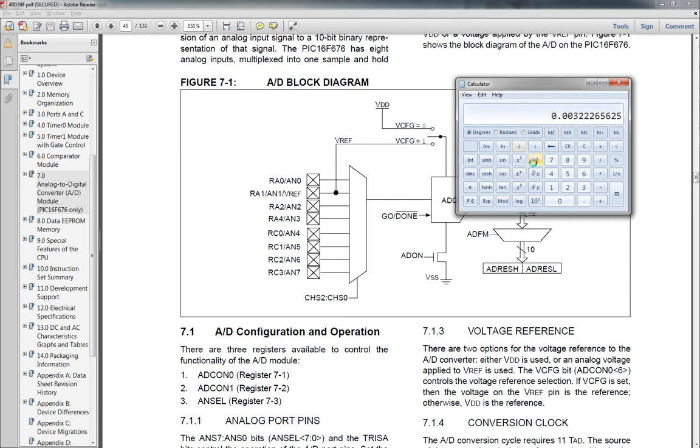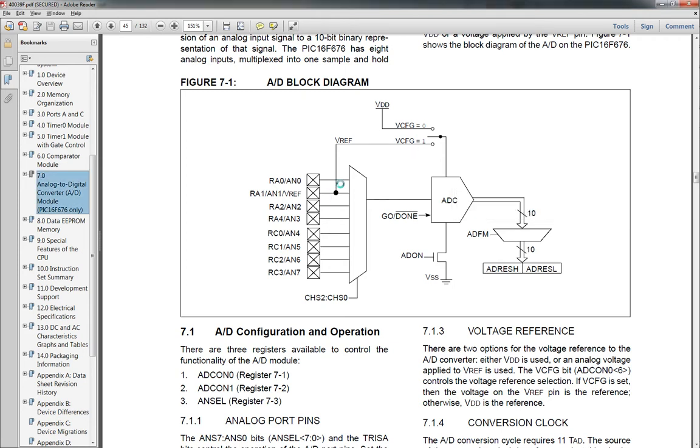So that's what the voltage reference is for. Like I said, you can have an external voltage, and sometimes it'll be the same voltage as what you're running at, 5 volts. But if you use an external voltage reference that's a precision voltage reference, let's say, it won't be real noisy, because a lot of noise can mess with your ADC and throw off your readings.